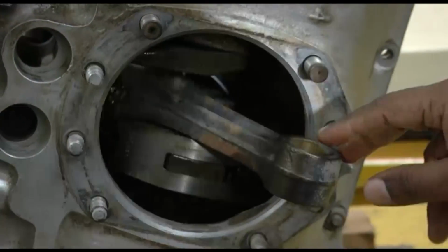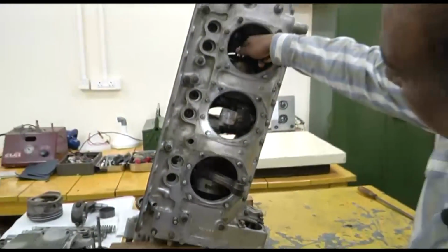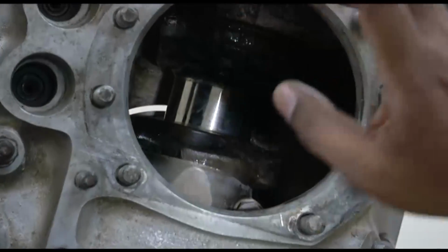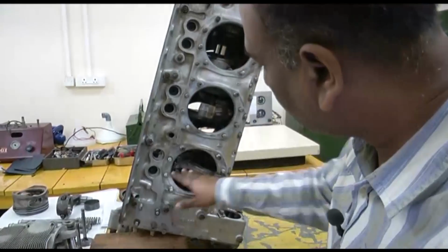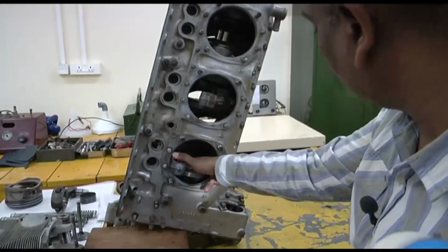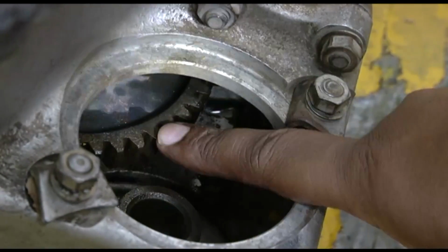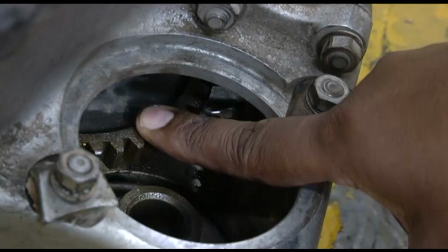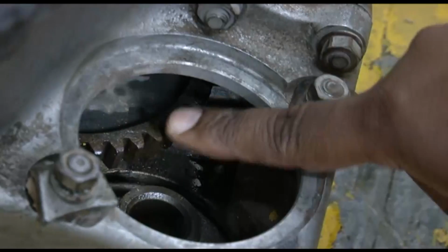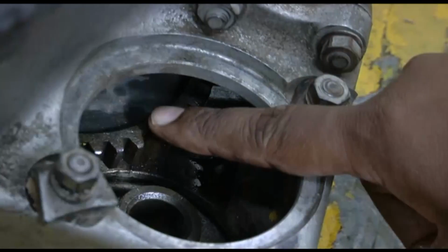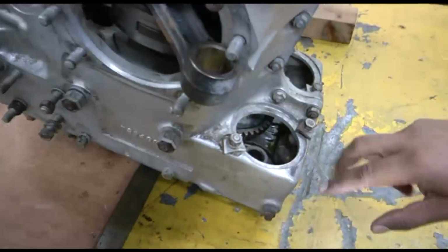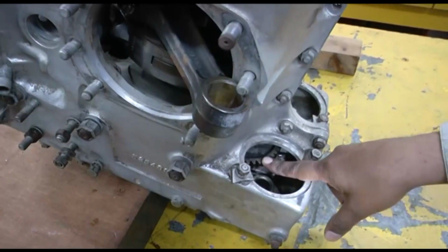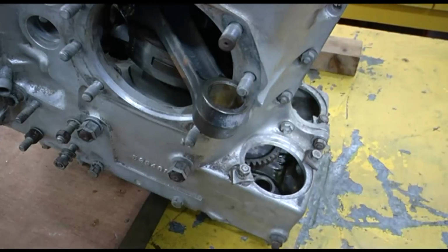So you've seen the crankshaft, the crank pin, the crank cheeks. Two crank cheeks and a crank pin make a throw. You've seen the counterweight with your dynamic balancing. So at the end of the crankshaft you have the crankshaft timing gear. This is your timing gear. It is a spur gear. So this crankshaft timing gear meshes with the camshaft timing gear. We have seen it in the front that there is a spur gear, another spur gear, and this crankshaft timing gear meshes with the camshaft timing gear.